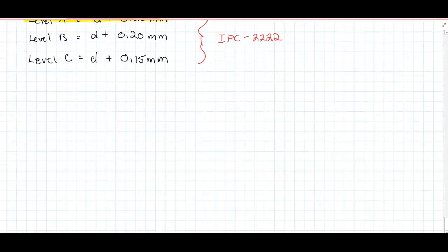Okay, now before we move on to some other standards that we need, let's talk about what a pad stack looks like, because a pad stack has several things in there. Basically, a pad stack is going to have the main components for a through hole. So let's look at a through hole pad stack.